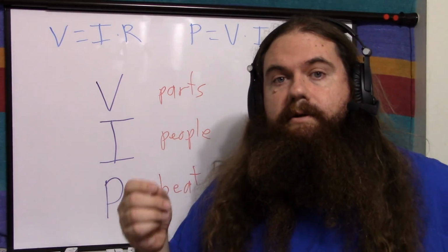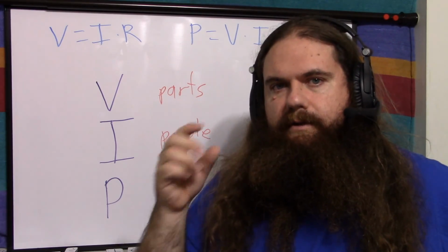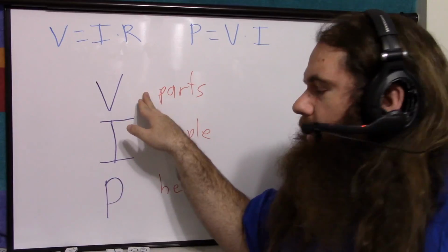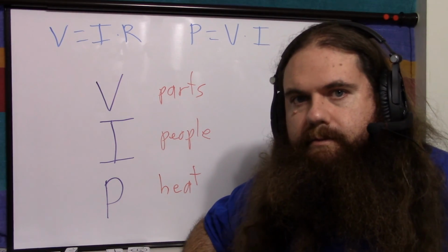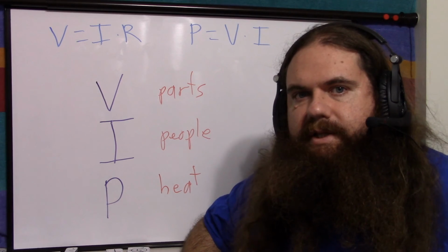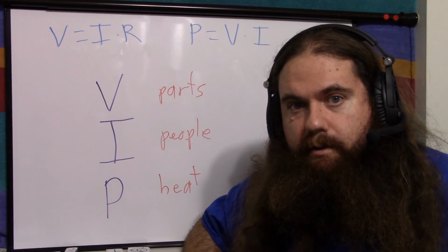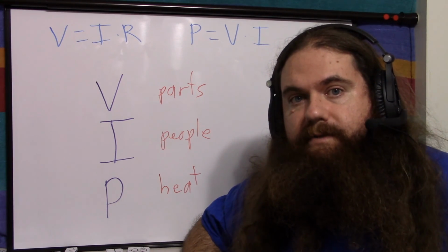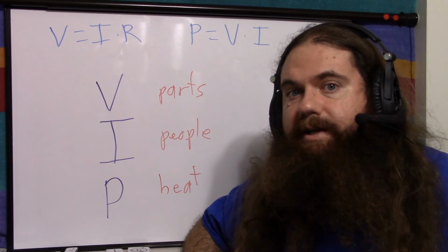But a transistor, even if you have very low current going through it, if you apply too much voltage, it will break. That's why I say voltage is dangerous to parts. And you say, no matter what, if you limit the current, limit the power, limit the heat, it'll be safe, right? No. That's why it's important that the oscilloscope, the voltmeter, is a passive thing. We can trust the device to generate only a voltage it can handle.